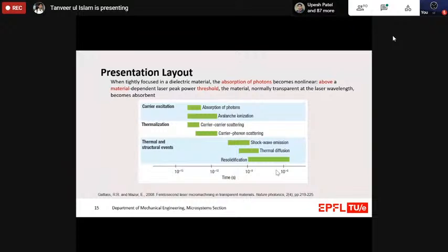When each pulse hits the substrate, it results in a whole lot of different processes in a very small time. Like I said, the absorption of photons happens initially, and then the avalanche ionization, that is, the electrons are smashed out of the orbit, and they result in the smashing out of even more electrons, and this way a chain of avalanche ionization happens. The important thing here is the thermal diffusion. When the pulse hits, apart from all other processes that take place in a very short time interval, there is the heat generated, but I said that the process is very special. It doesn't allow the modification of the material thermally. The heat generated by each pulse is dissipated in less than 1 microsecond.